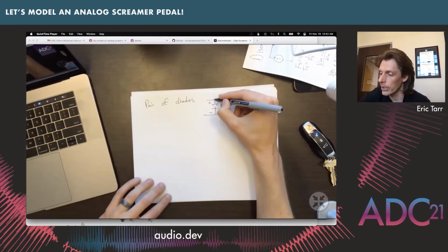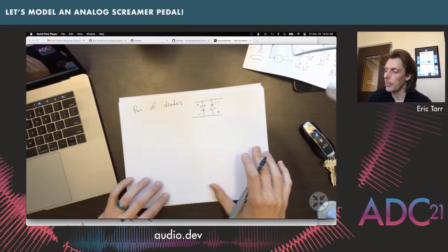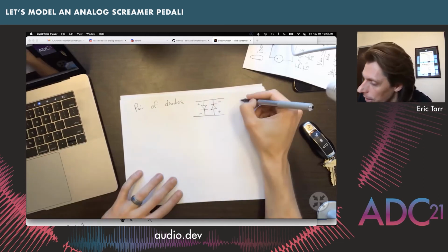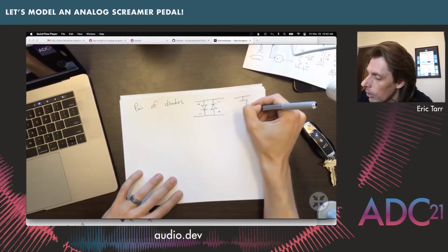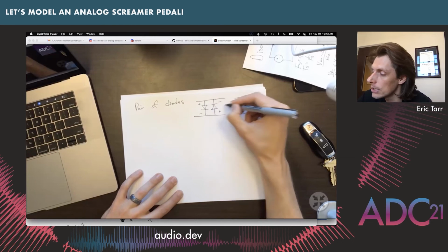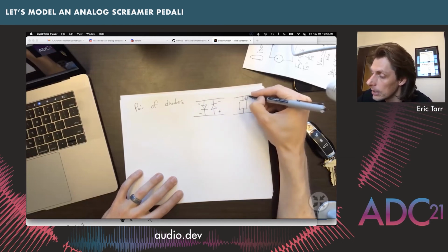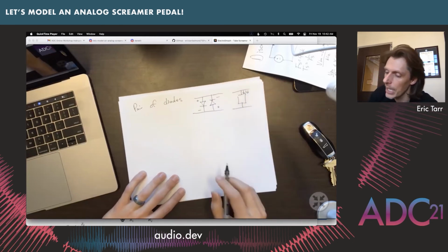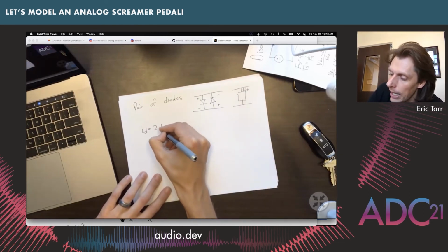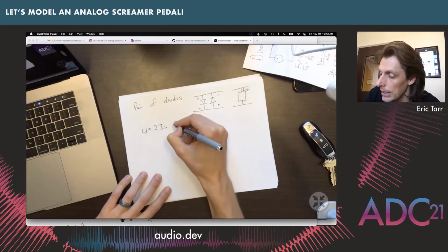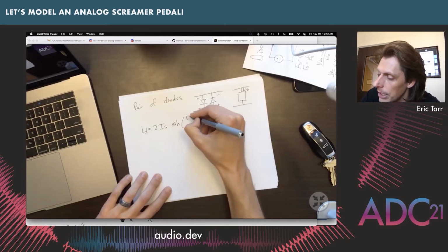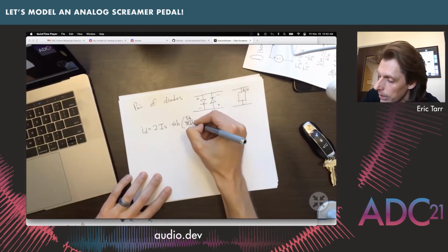And you could write out all the currents to go through each one of these separately, but there's a nonlinear equation that works if these two diodes are identical to each other, where you can write it as a single block for both, to model both diodes together as a single current ID through both of them. In this case, our diode equation becomes 2Is times the hyperbolic sine function of the voltage across them, VD, divided by eta VT.